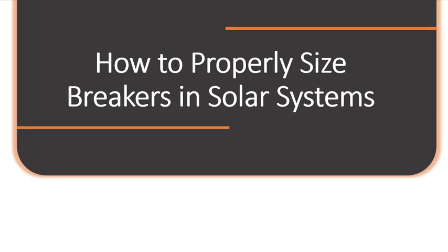So in this lesson we are also going to look at the common mistakes you should avoid when sizing your breakers, and a lot of installers have been making this kind of mistake. So I'm going to walk you through some of these mistakes that you should avoid when you are sizing your breakers. Now before we start, let's discuss why we need breakers in a solar system.